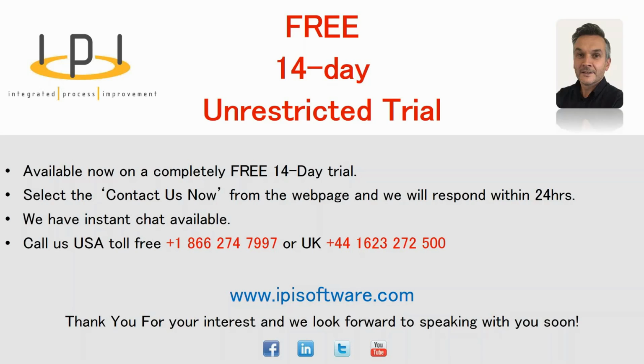If the question was, if I go back into FMEA, will I see a change if I've changed the op number or if I've changed the feature number that I've linked it to in Process Flow, will it be changed in Visual FAIR? Then the answer is yes. So at all times, any changes you make in the software, it will link and feed back to other applications. But just be careful, documents you create can be, as you're aware, PDFs or Excel, they're then out of the system and they're on their own. So nice question there.